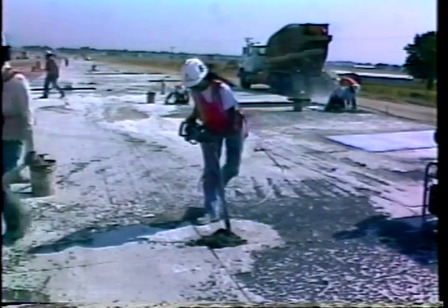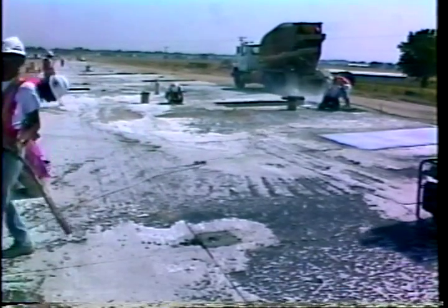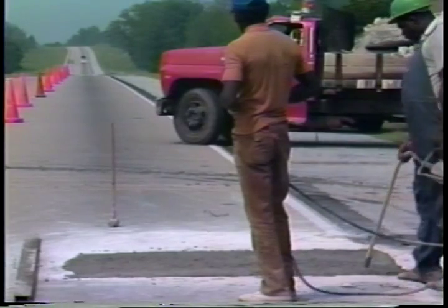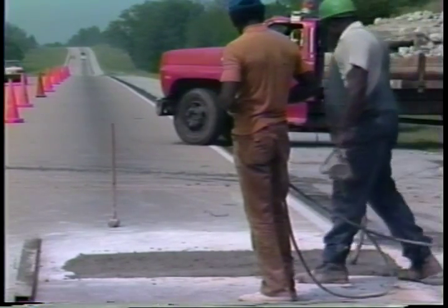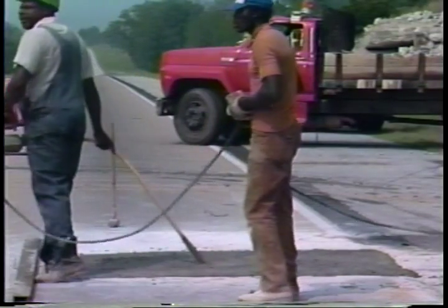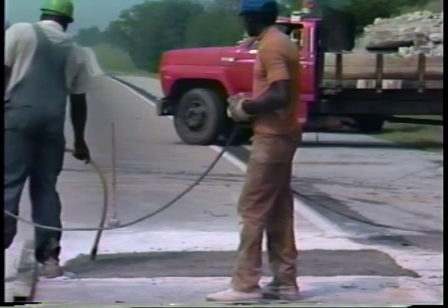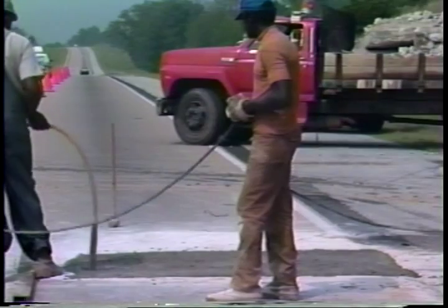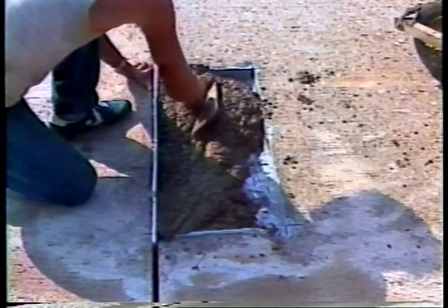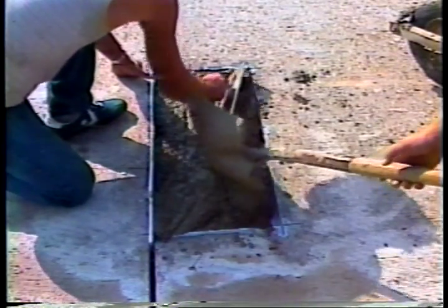Vibrators less than 1 inch in diameter are typically used to consolidate the material. For proper and complete consolidation, the material should be vibrated by dipping the vibrator vertically into the material at locations throughout the repair area. When moving from one location to another, the vibrator should be lifted out of the material, not dragged through it. For very small repairs, adequate consolidation can be achieved by rodding and tamping and cutting with a trowel or other hand tools.